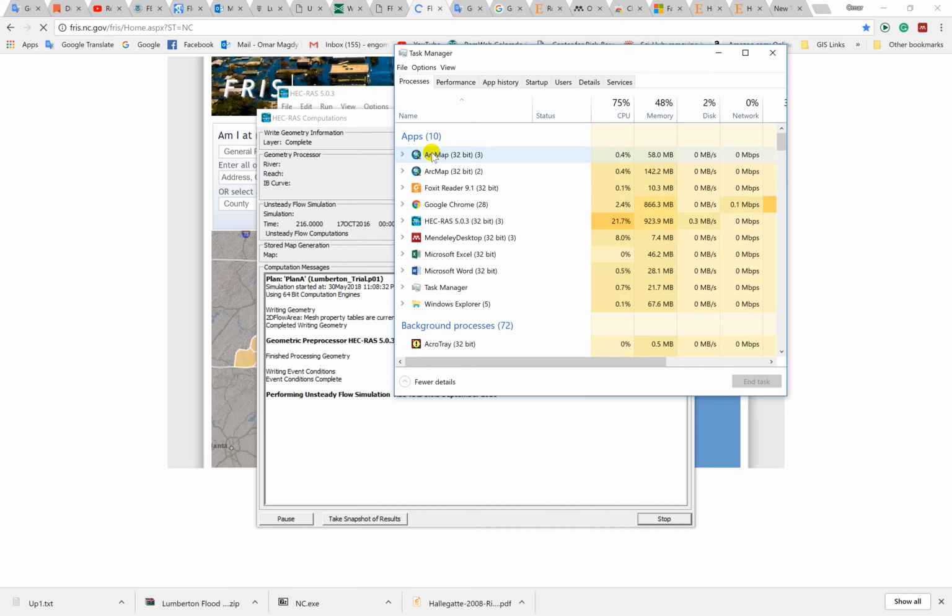But what I used is just the policy of HEC, the concept of HEC, to calculate the loss estimation. Also, I used the formulation for losses, because this is really easy. You just need to multiply the percentage of damage times the replacement cost. So you need to have the replacement cost, and also based on the value of the building and the characteristics of the building, you will get the percentage of damage. And this is the code. Let me explain. I get the percentage of damage from the flood characteristics and the building characteristics.